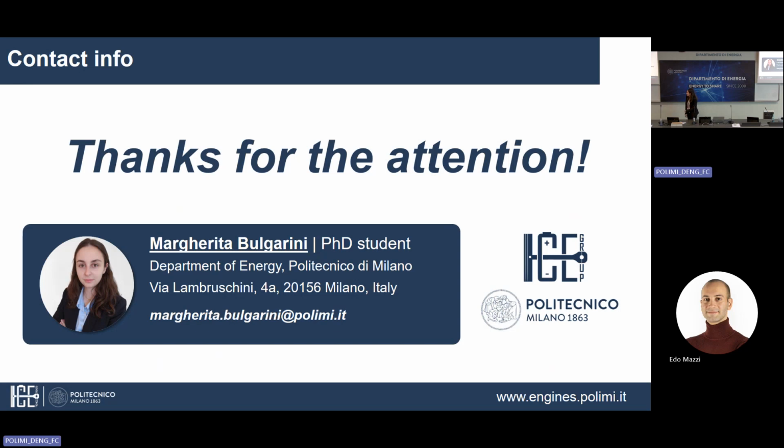Of course, computational time is higher with a 3D analysis, but we have examples in literature of 1D analysis, and they are pretty good to study the consumption of reactants from the inlet to the outlet, for example, or the performances of the component. But of course, with a 1D model, we are not able to study in detail the diffusivity of reactants, for example, under the rib, so in the porous media. And a 3D analysis can give interesting insights for the study of the degradation mechanism due to an in-plane distribution of, for example, reactant concentrations.